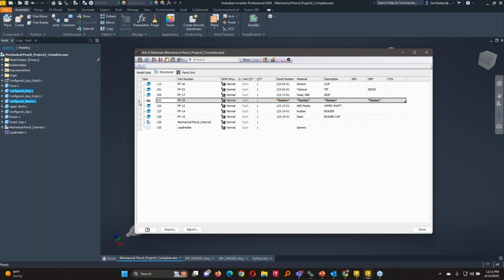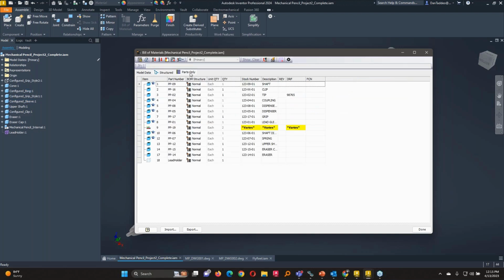And if I go back to the parts only list, you're going to see that it still shows those 2 components, it's organizing by the part number. Now, one thing I can do to fix this is go into the properties of these guys here, opening the files and editing them from there. I can go and tweak the sort. Right now, they're automatically merging the cells together.